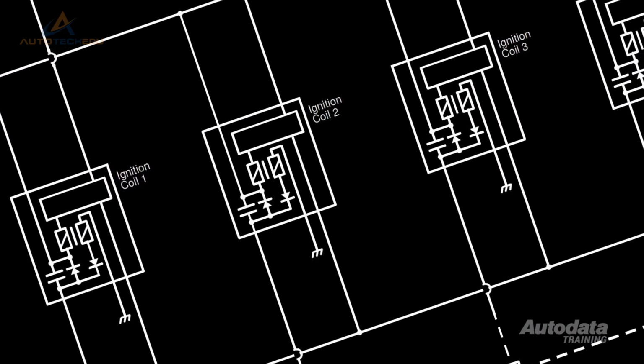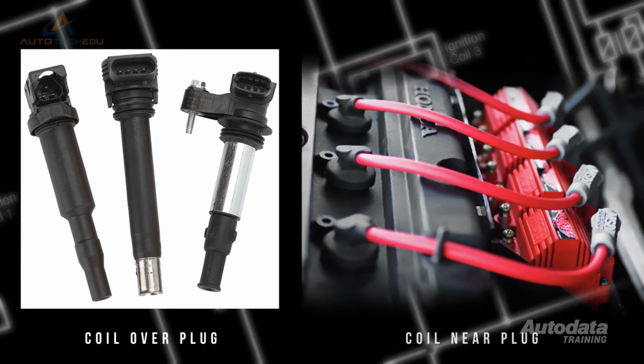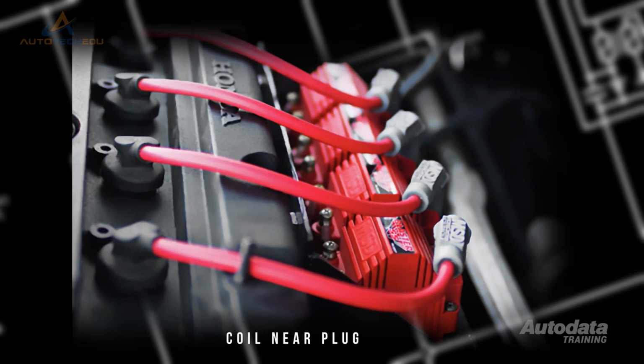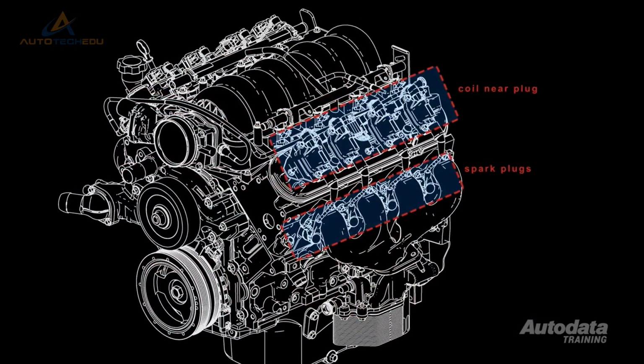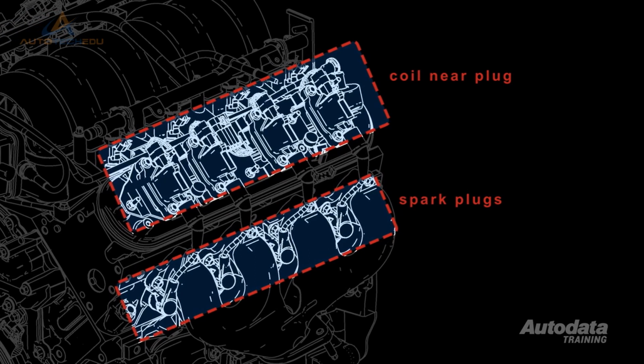The operation of a coil per cylinder ignition system is basically the same as any other type. By definition, there is one coil for each cylinder. There are 2 different types of coil per cylinder systems used today: the coil over plug or the coil near plug type. The main difference is a coil near plug type needs a high tension lead to connect the coil to the spark plug. These systems are used when the location of the spark plug does not allow enough room to mount individual coils over the plugs, or when the spark plugs are too close to the exhaust manifold.